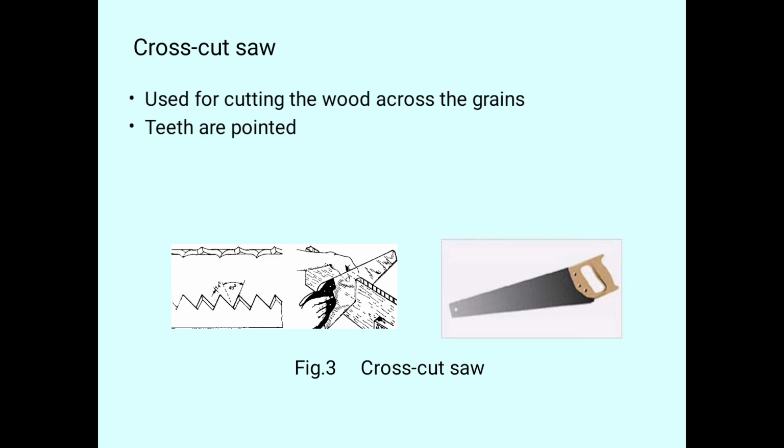Okay, it's not like a chiseled edge, but the teeth are pointed. The pitch of the teeth is about 2.5 mm to 3 mm.